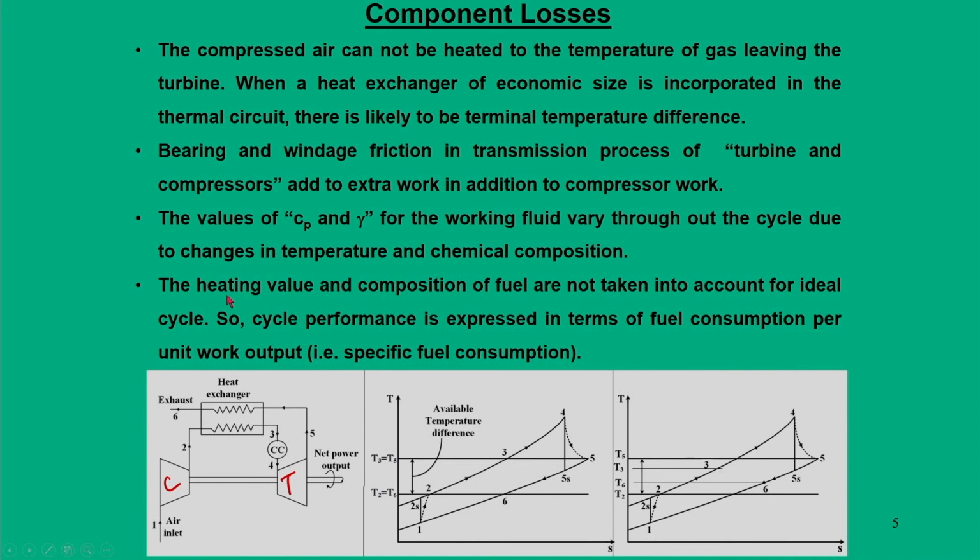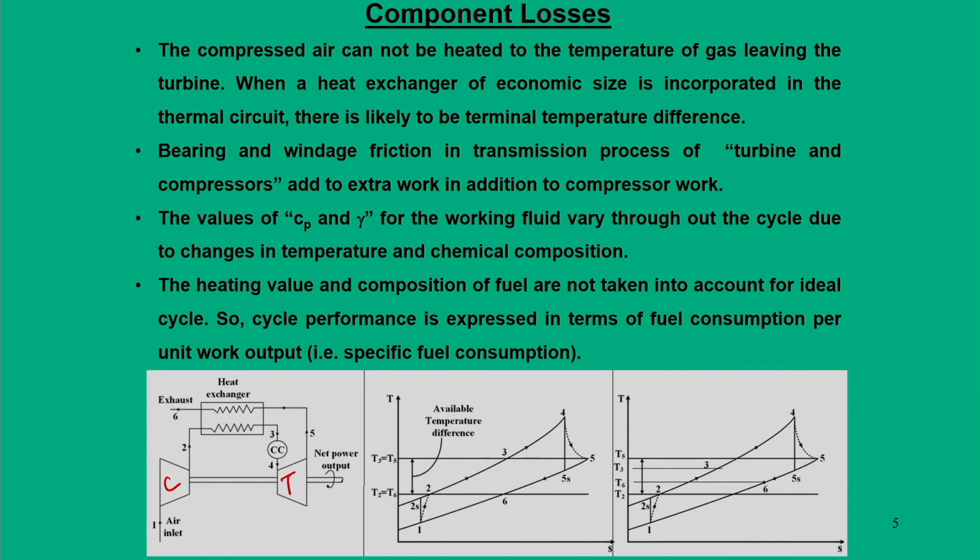Another issue is that the heating value and composition of the fuel are not taken into account in the ideal cycles. There we simply said that we just added heat in terms of fuel, but fuel has no role except to add heat to the system. But when you quantify how much fuel is added, then we should be worried about specific fuel consumption. That means how much fuel you require per unit work output. So, all these things need to be accounted for.